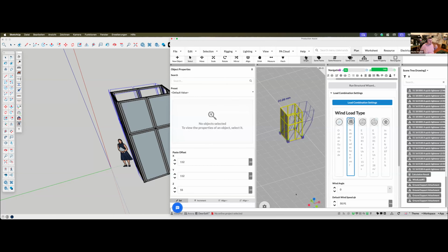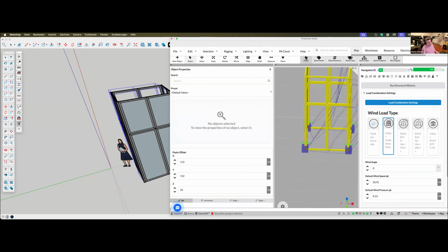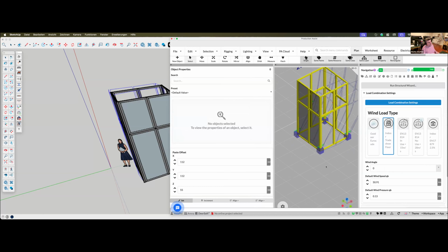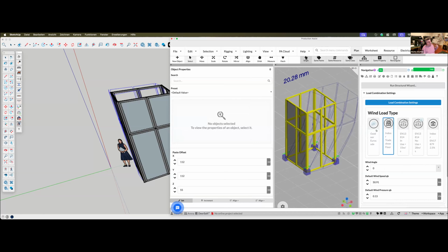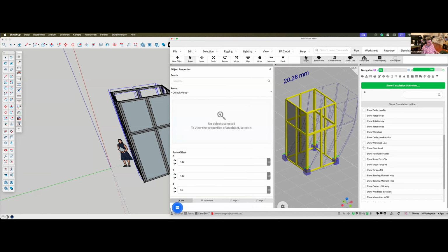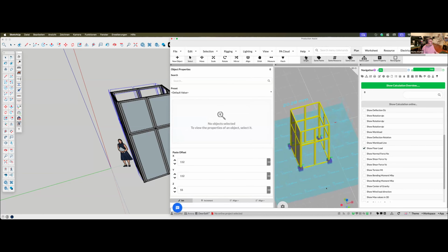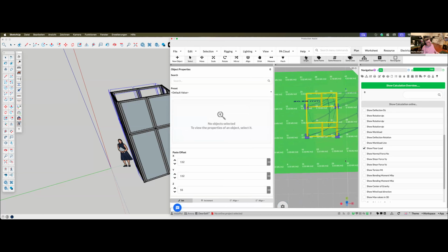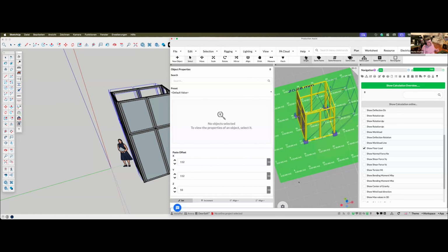But you can also create the reports yourself. And that's basically what we're doing here as the next steps. So I already did the calculation. I checked that I have calculated the right amount of ballast. I've checked that my truss structure is not overloaded. That's at 74%, so the amount of corners that I have is totally fine. What I can also check is, when I click on show floor loading, it shows me the resulting floor loading that I apply to the floor. So this is also in the green area.